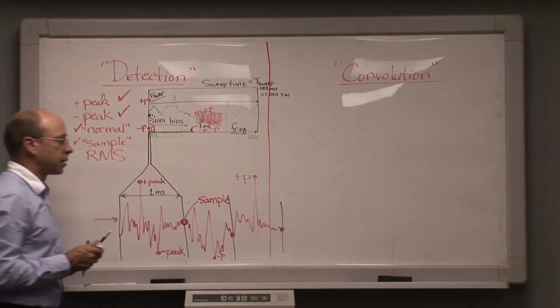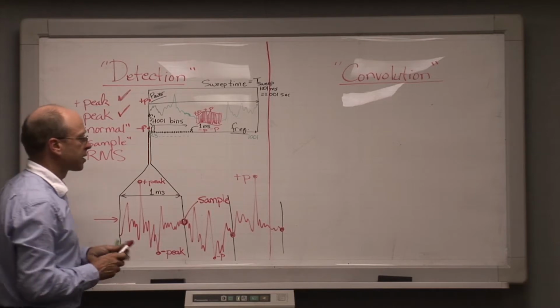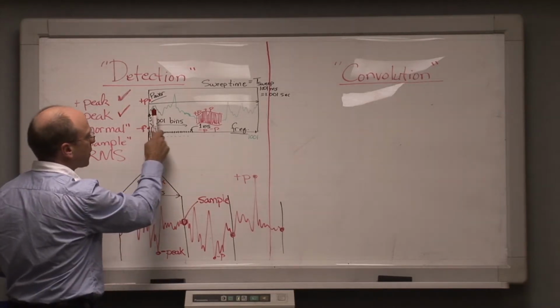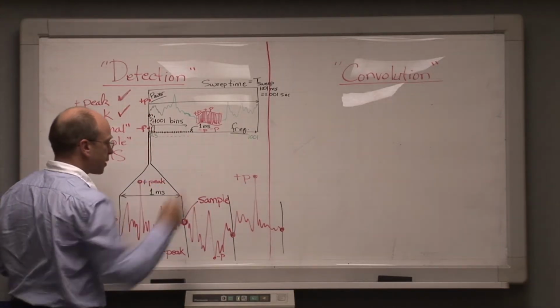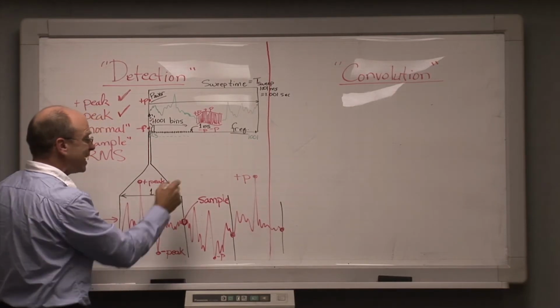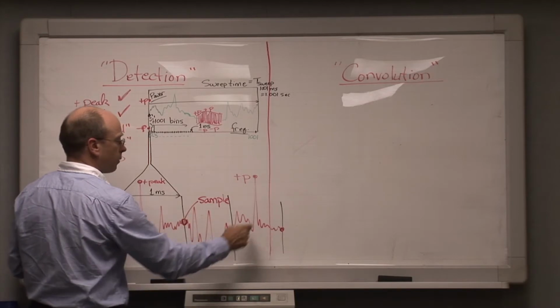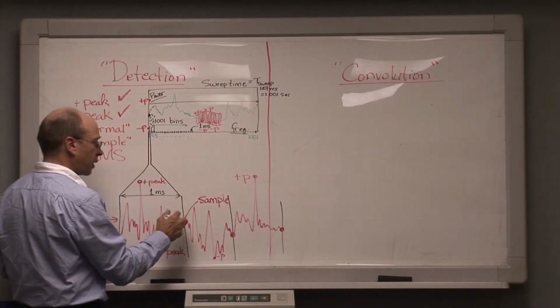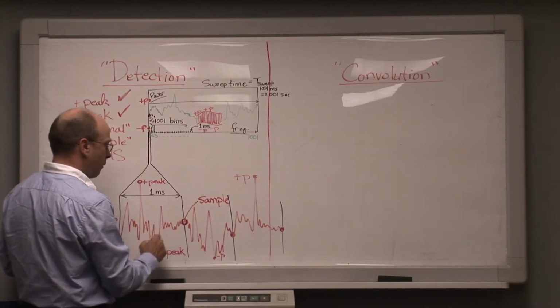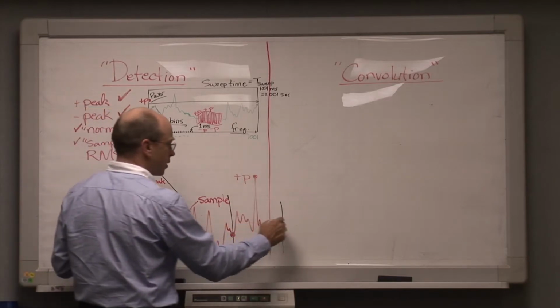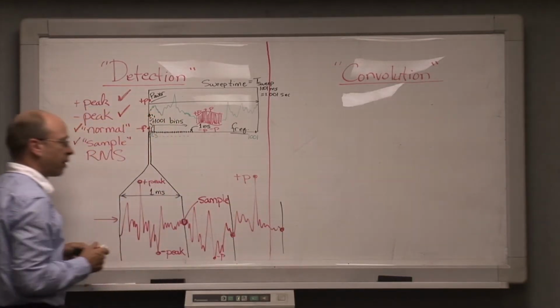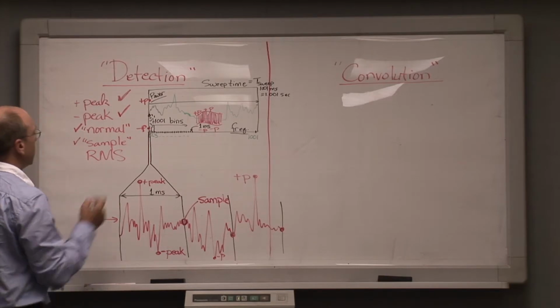And so, as long as the waveform that we're measuring is not in some sense correlated with the rate that the spectrum analyzer is sweeping frequencies across these bins, sample detection in effect gives us a random sampling inside the waveform because we're simply picking off the nth power value available in each of the bins, the nth being the last power value that each bin saw.